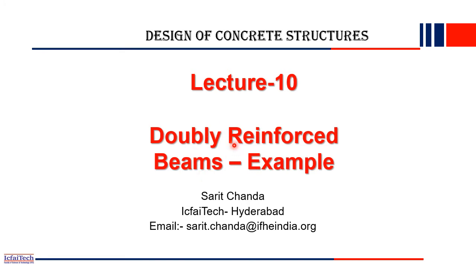At this point, I hope you have understood what a doubly reinforced beam is, and when we need to provide it. When the singly reinforced beam is not adequate to take the loads, that is when we provide the doubly reinforced beam. For example, a beam, let me draw it here.